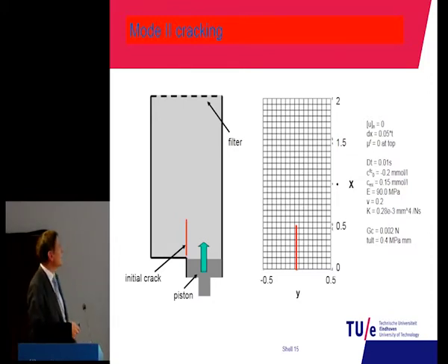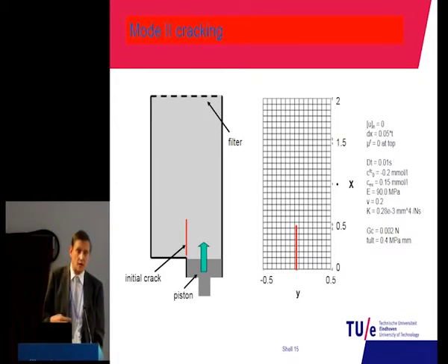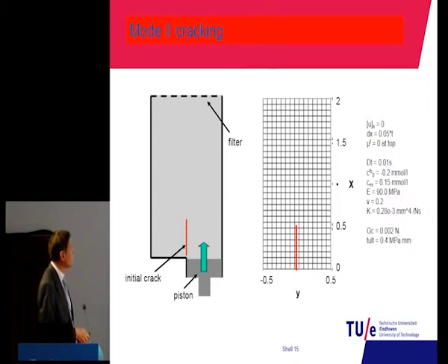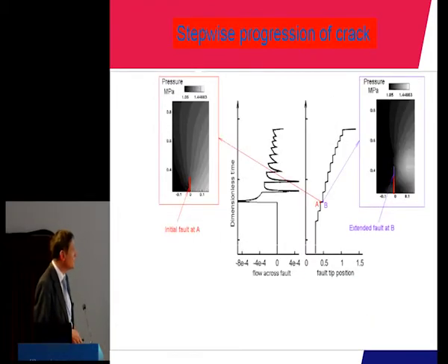So we can actually do a comparison between experiment and analytical solution and numerical simulation. This is for the situation of free swelling. So we contact a 1D domain with a sudden change in salt concentration, and what happens is the material swells. You have changes in electrochemical potential, electrical potential, pressure, etc., concentrations. All of these are changing at the same time, and we can reasonably catch this using mixed hybrid finite elements. Using the regular UP formulation, it didn't work this way.